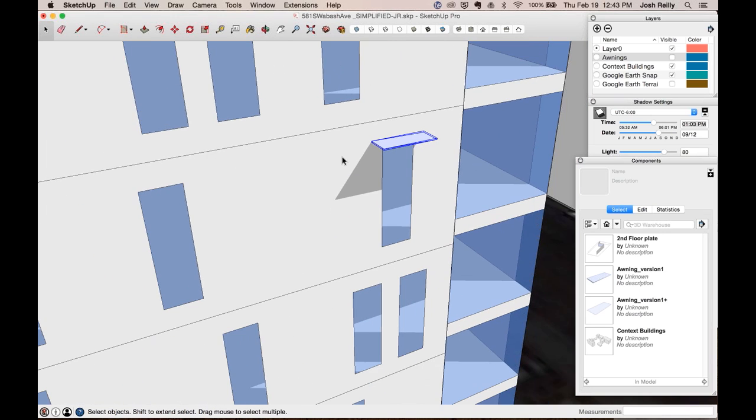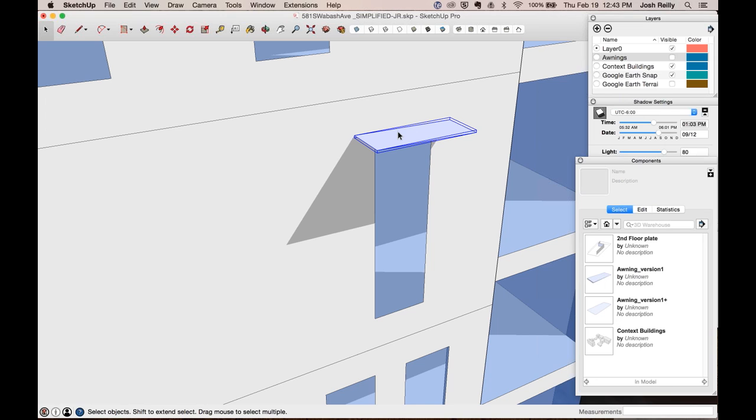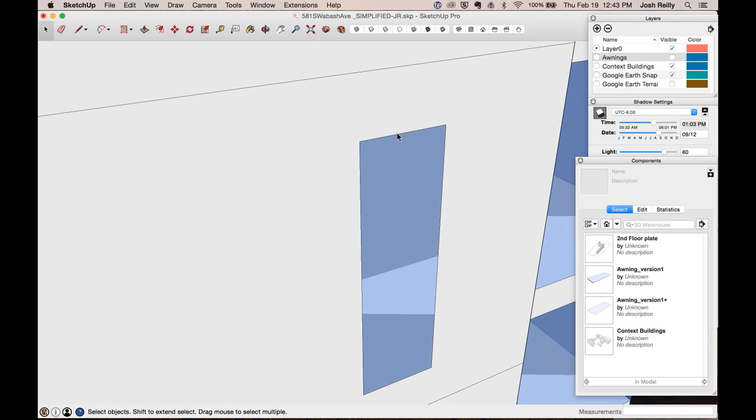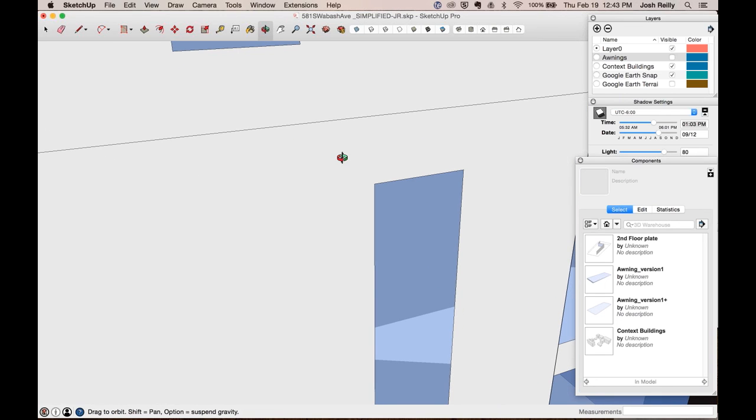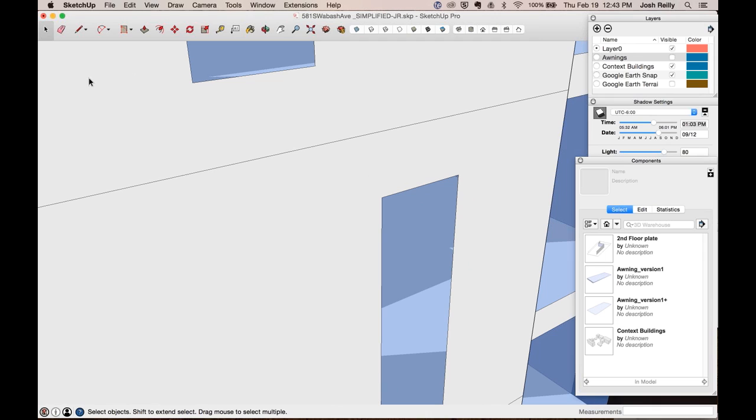You know what, I'm going to go back and redo that to show you guys one more time, just in case I breezed through that too quick for some of the new SketchUp users. Go to the rectangle tool, rotated rectangle, hover on this part, start the rectangle there. I know I want to go 4 feet in this direction and come out 2 feet in the red direction.